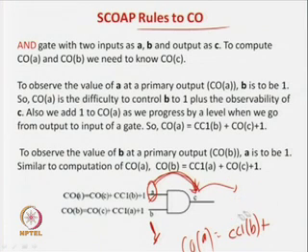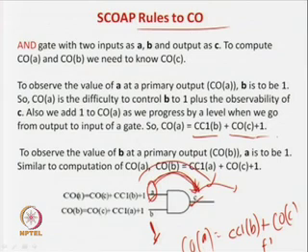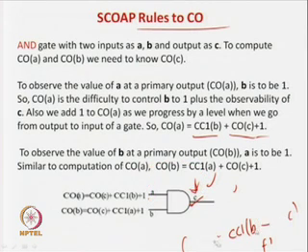That is equal to the combinational observability of C, because it tells you how difficult it is to observe C at the primary output. So, combinational observability of A is equal to combinational controllability of B to 1, you make B 1, the value of A is reflected at C, and we know how difficult it is to observe the value of C at the primary output, that is CO of C. Plus 1 you have to add, because there is a level shift. So, CO of A is equal to CC1 of B plus CO of C plus 1, where 1 is the level shift. That is what is said in the line I have explained.